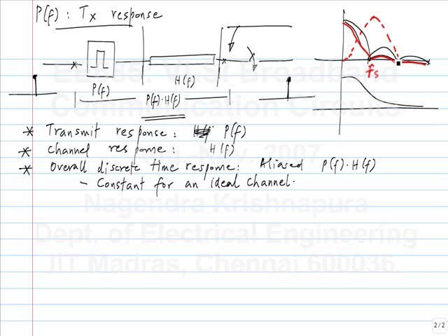Why do we have to sum over an infinite number? What is the reason? That's because of sampling, right? This is more of a mathematical operation. Once you sample it, you are summing over an infinite number of copies. It is not related to the bandwidth. At least that's how you get the result mathematically. It doesn't mean it will take you infinite time to do it. It's not something that is happening over time, and not some summation happening as a sequence of summations of two terms. It's just that the effect of sampling can be represented as an infinite summation.